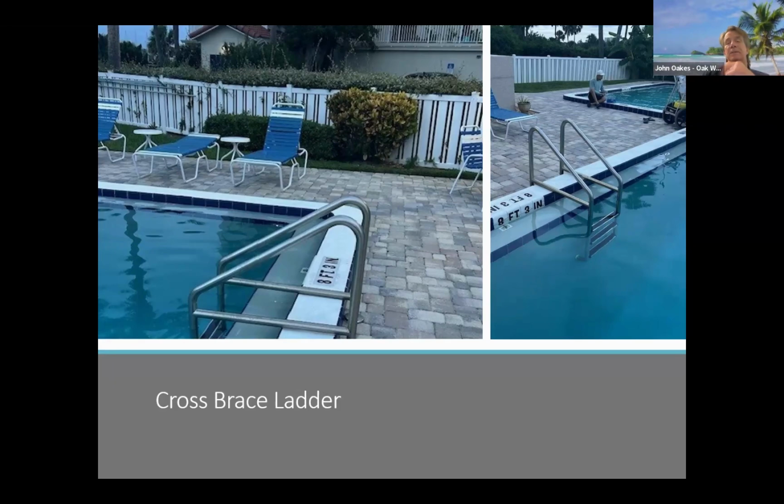The gutter, which is the ledge that's underwater there, has specific dimensions that it has to meet, and those dimensions could change during a renovation because the demo guys are going to chip the gutter out and chip the tile off the front of it. That gutter has to be 12 inches wide at a minimum.